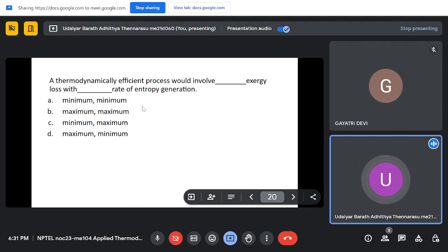Exergy loss is basically what you are not able to get out of the system, which you have lost to friction or by some other means. The definition of exergy is the maximum amount of work which you can get from a fluid at some temperature and pressure, when you bring it to the ambient condition, the dead state. The maximum energy which you can get while doing the process reversibly is exergy. So that is the maximum which you can get.